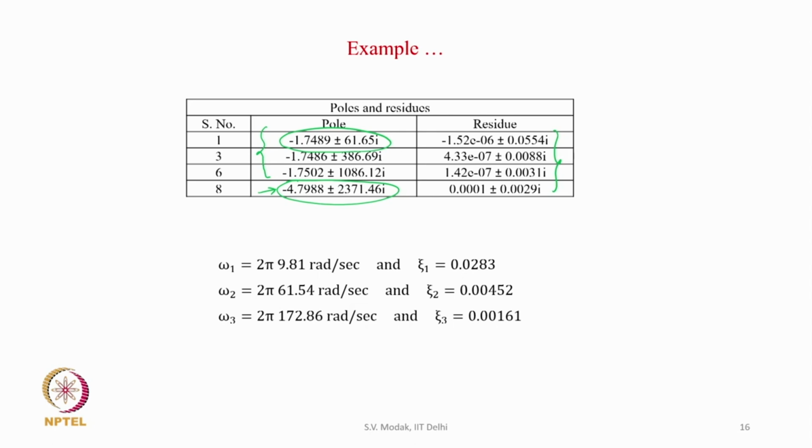Let us now look at the quality of the curve fit we have been able to achieve. For that, let us overlay the FRF regenerated using poles and residues, because once we have found the poles and residues for the FRF H55, we can use them to reconstruct the FRF, and then compare that regenerated FRF with the measured FRF that was curve fitted.